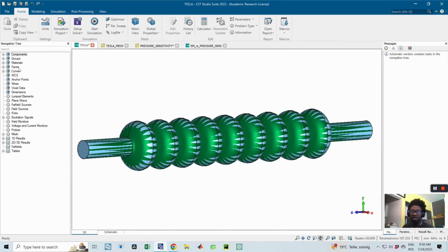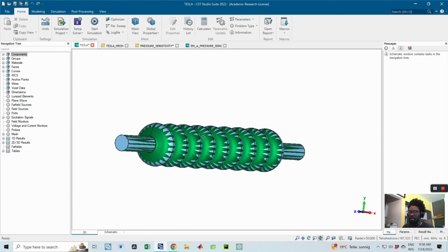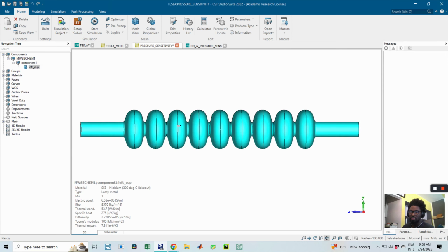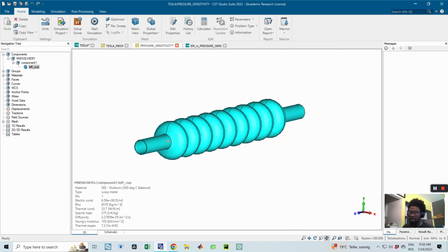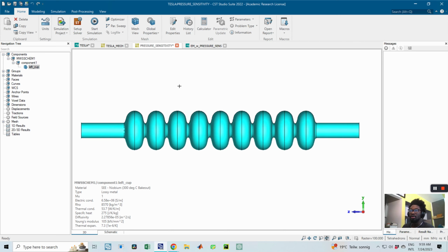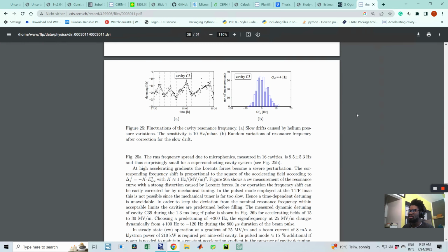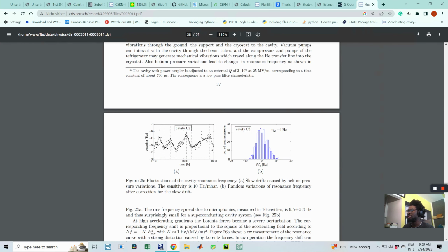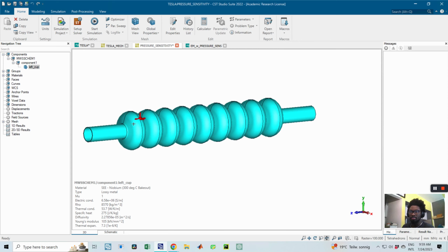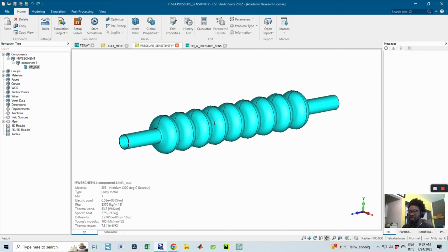Don't mind the grid stuff, it's a face. I started from this, which is set up for ideal mode simulation, and this is vacuum, and then shelled my cavity already and applied niobium as the material of the cavity wall. I also set the thickness to, I think, 2.5 millimeters, as recorded in this paper, which references the last one. I would also put the link in the description.